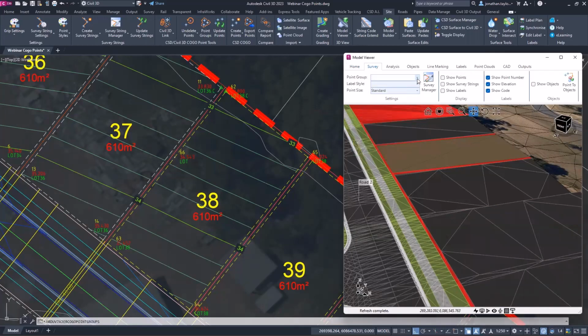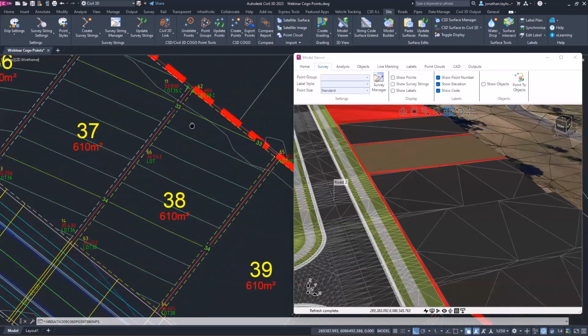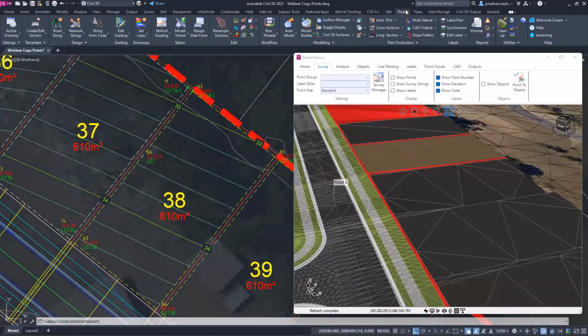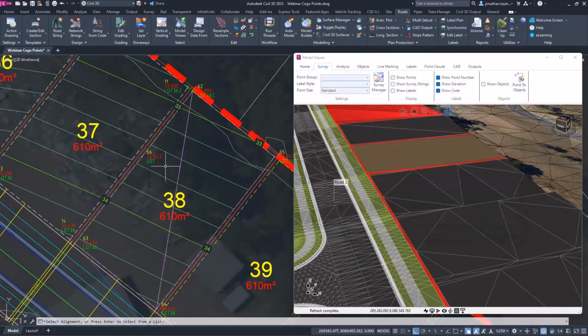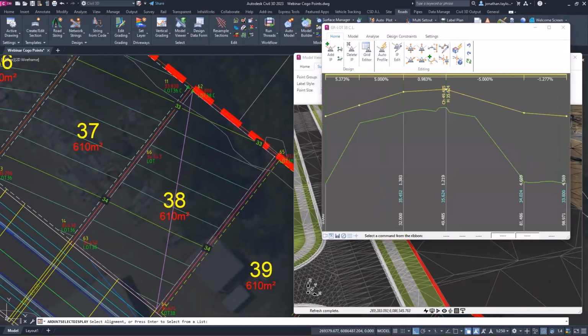And if we wanted to add point 66 to that grading surface there, then the way... Well, it is in mind to me. Well, is it? Because if you put the triangles on for that surface, so just... Well, it's an IP. It's an IP on that surface. So if we go and find lot 38. Yeah. See the triangles. It's not. I see what you're saying. Yeah, now I'm with you. So the only way to add it in that I could think to do it would be to add an extra sample point in there in the polyline itself, because it's the vertices of the polyline that control it. That's a very good point.